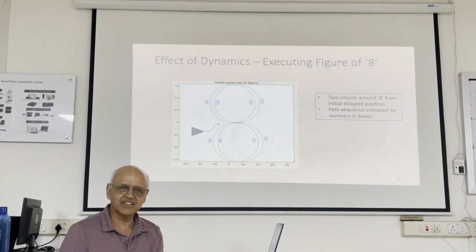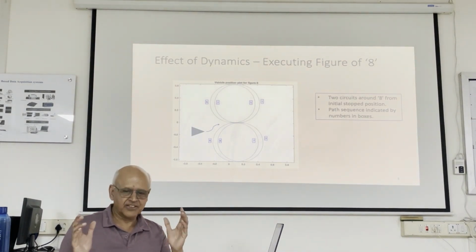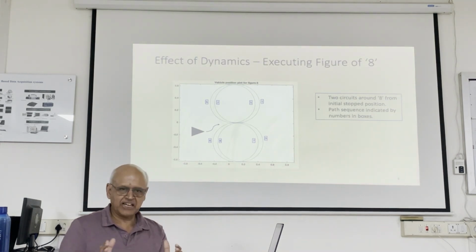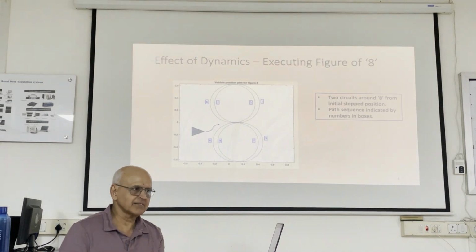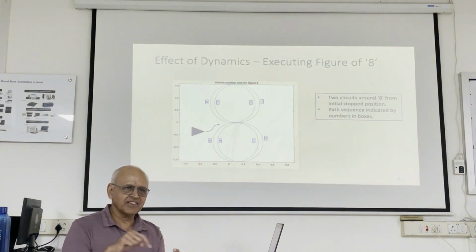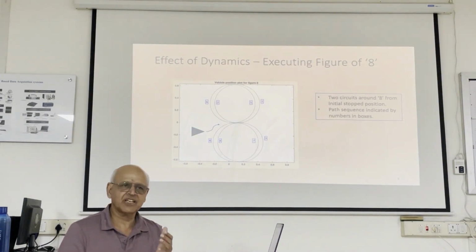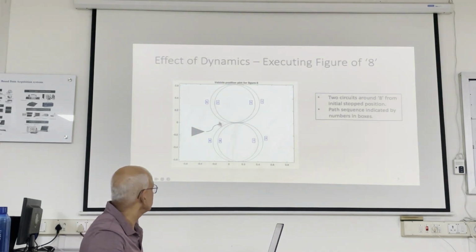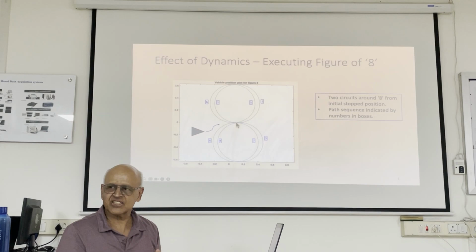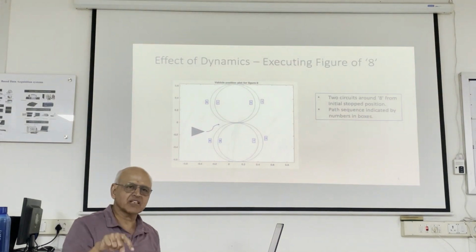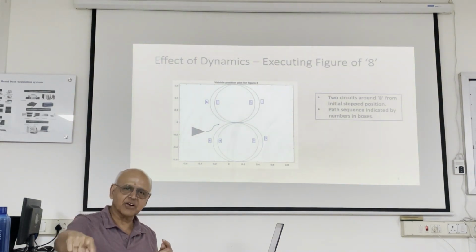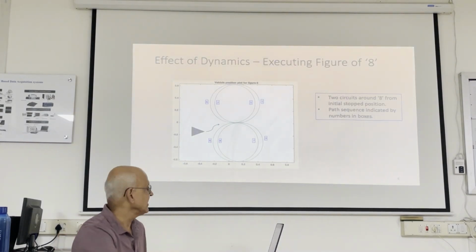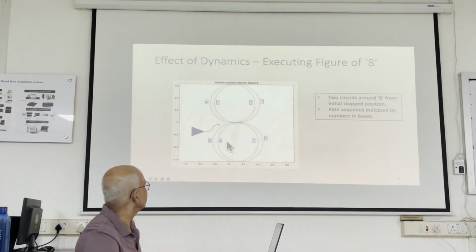So isn't it true that the right wheel is going to take longer? Like, first of all, they're going to go exactly next to each other, right? Till they reach the lower of the 2 velocities. Doesn't that make sense? So what does it mean? These 2 are going at the same speed till the lower of the 2 velocities. It's going to go initially straight. So even though you expect it to be on a circle, it won't get to that circle. And in fact, if you blow this part up here, you will see that it's actually going straight till the lower of the two velocities is reached. Then the right wheel keeps on going, the left wheel has reached its target velocity. And then it starts to get on the circle.